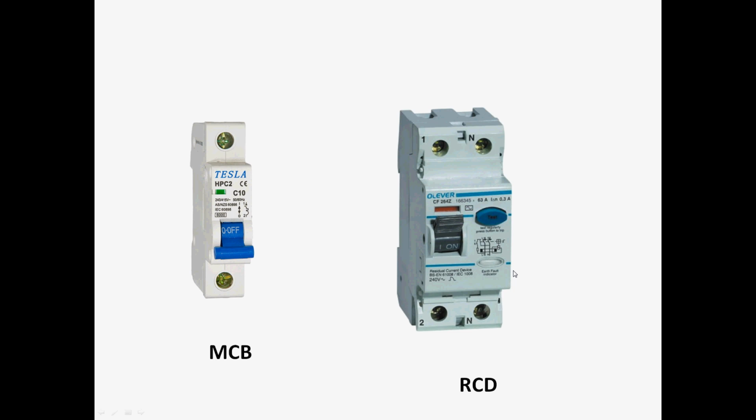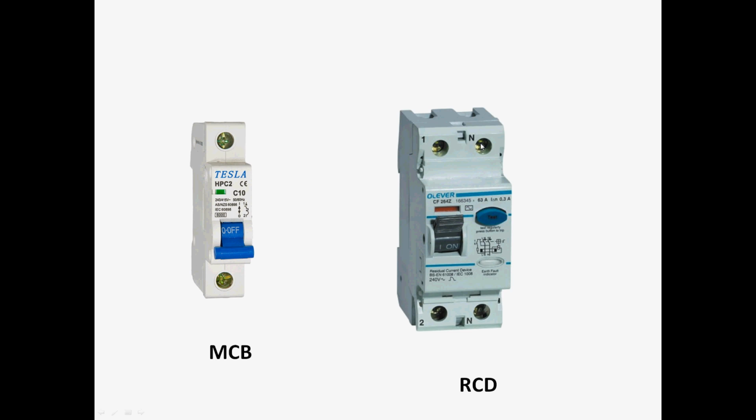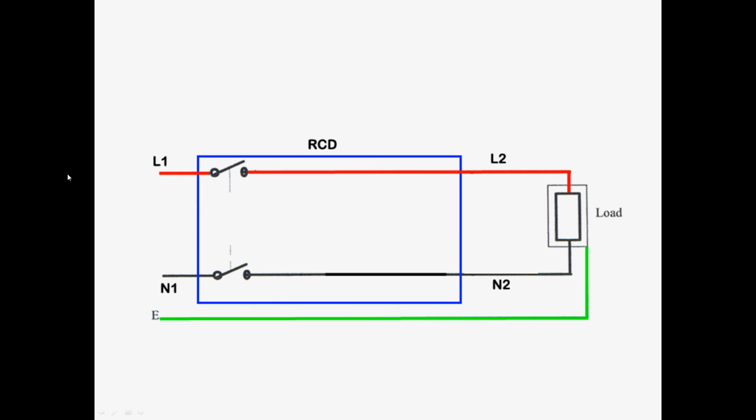You can see an actual picture of an RCD, and you can compare it with a normal circuit breaker or fuse. The fuse or a single pole circuit breaker, as I said, has only two terminals, one for incoming line and one for outgoing line. Here you can see that the RCD has four terminals. One is for incoming line, this is for outgoing line, and this is for incoming neutral, and this is for outgoing neutral. Both line and neutral need to be connected to the RCD.